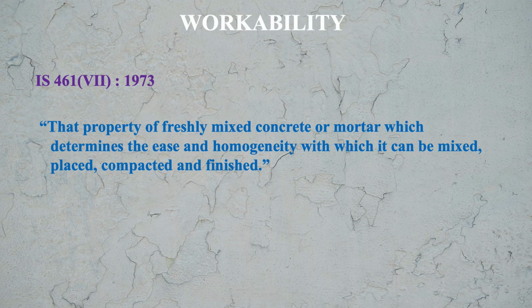If we go to the definition given by the code IS 6461 part 7, 1973, as per the code, workability can be defined as that property of freshly mixed concrete or mortar which determines the ease and homogeneity with which it can be mixed, placed, compacted and finished. So this is the definition given by the code.